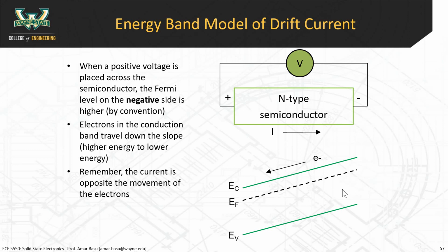Notice that we've kind of done that. The particle model has to do more with a physical model. You can try to picture small particles, you can picture the lattice, and you can picture things moving through the lattice. So you can think about it as a physical model. I want you to have a physical picture of the phenomena that are happening, and I also want you to have the energy band picture of what's happening. The energy band model derives from Schrodinger's equations. It talks about the different energy states that an electron can have. All right, so this is an example.